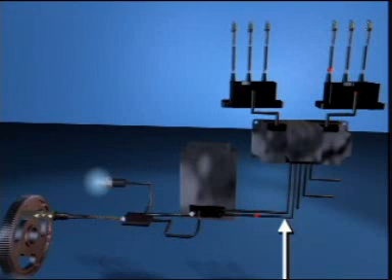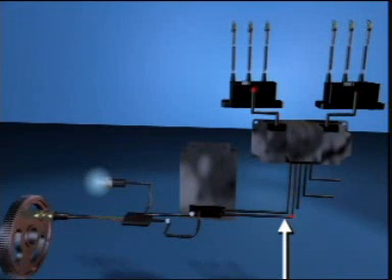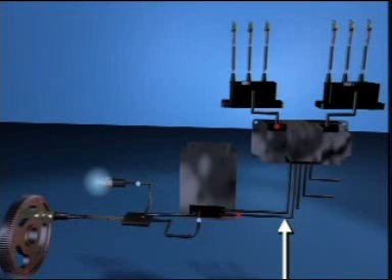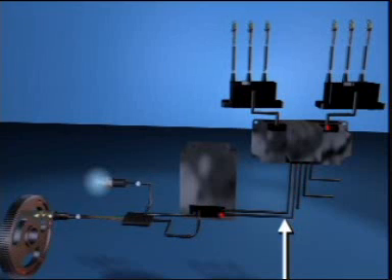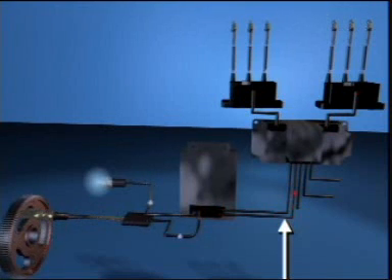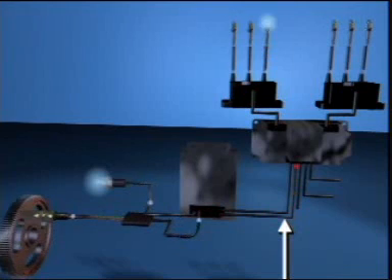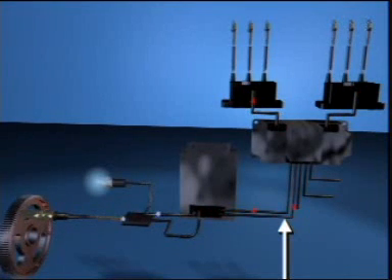The spark timing signal to the ICM defines the ignition timing for each cylinder. The timing signal is defined by the intake manifold pressure sensor and the engine position sensor inputs. The ECM uses these signals to make timing adjustments and sends a spark timing signal to the ICM. Using the ECM to control engine timing eliminates the need to check or adjust engine timing.